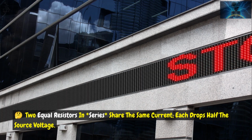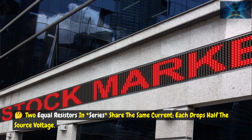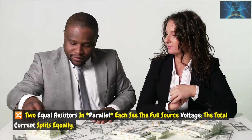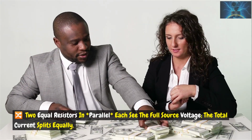Thought experiments you can run in your head. 2 equal resistors in series share the same current. Each drops half the source voltage. 2 equal resistors in parallel each see the full source voltage. The total current splits equally.